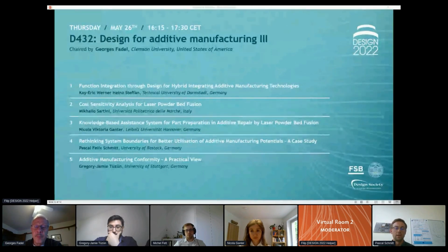And yes, of course, in addition, the product was manufactured using FDM, and the influence of the manufacturing behavior and, for example, anisotropy wasn't taken into account, and this may lead to the safety factor actually having to be increased, which would lead to increased weight again. So it can be seen as a prototype, I think.